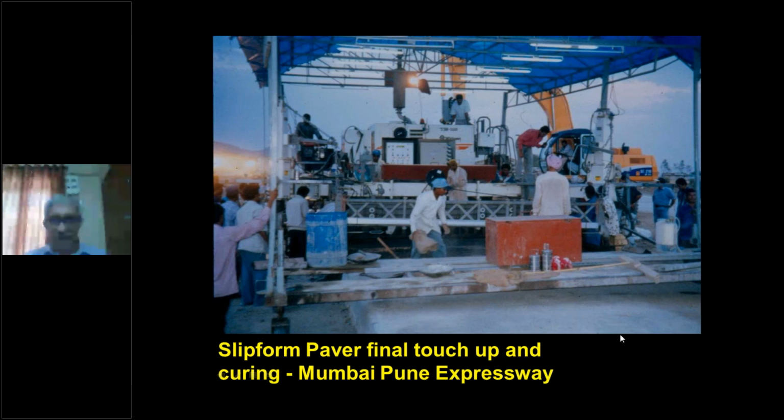They used to spray the curing compound as well as do some small repairs in case the mix had not come out properly. The touch-up was required and curing immediately was necessary.